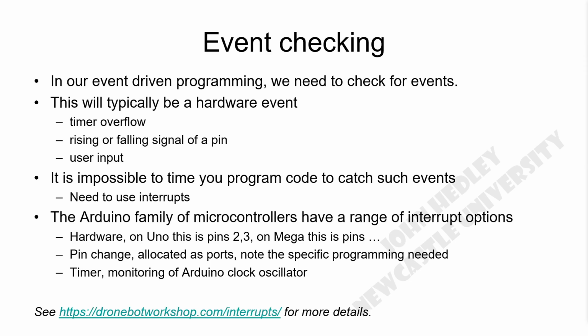The Arduino Uno has 2 interrupt pins, these being digital pins 2 and 3. These can be triggered on a rising or falling edge, by a change in state, or by when the pin is low, the latter being a state rather than an event. The Arduino Mega has 6 interrupt pins, these being pins 2, 3, and 18 to 21, although with limitations.